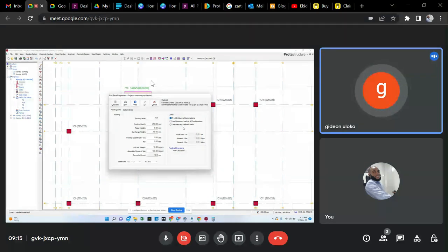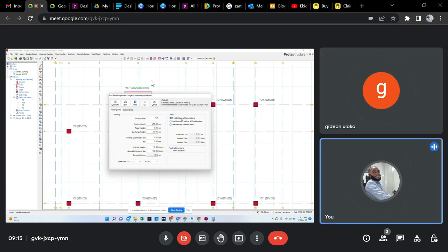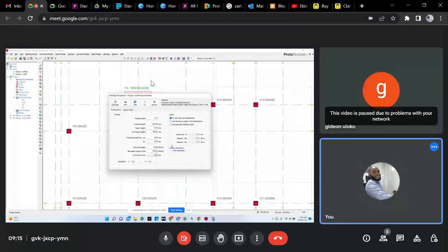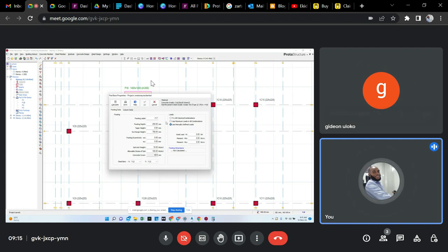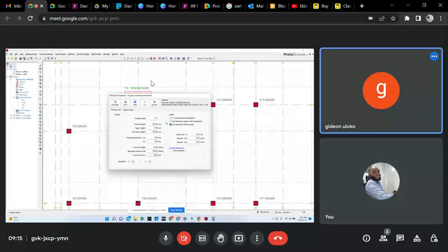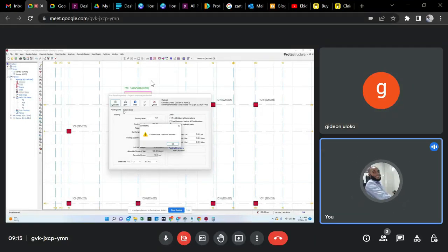I should click on Calculate now. Okay, now hold on. Click back on that, use a manual defined load first. Let me show you something. Now click on Calculate. You see an error issue. That's because axial load is not yet factored.